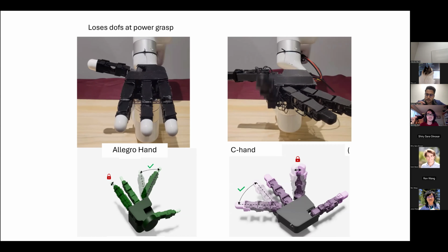And we show a bunch of different results here. This is me doing teleop from one webcam, and we're able to do teleop on a bunch of different tasks just by using one webcam. And we beat the Allegro hand baseline pretty easily on these tasks. And we also show autonomous results as well. So here we use some internet videos. We pre-train it to give the robot an idea of what the human hand motions are in the videos. And then we use that as pre-training and then fine-tune on a few teleop demonstrations.